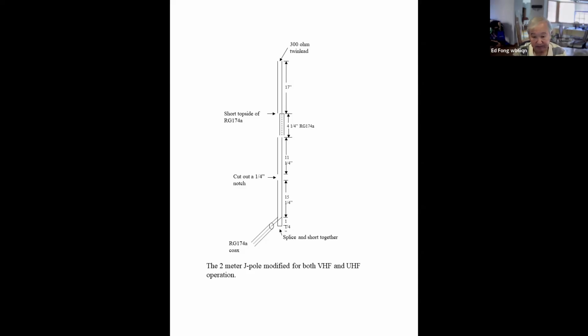I think I showed in the last lecture how it works. Every half wave, you come back to the same point on the Smith chart. So if you make an antenna that resonates at, let's say, you make a dipole at 100 megahertz, and now you have this NanoVNA, you can sweep it. At 100 megahertz, you build a dipole, it dips. It will also dip at 300, 500, 700, and eventually other things come into play, the losses, and sure, it won't go on forever. But certainly the first few harmonics, you will see it dip.